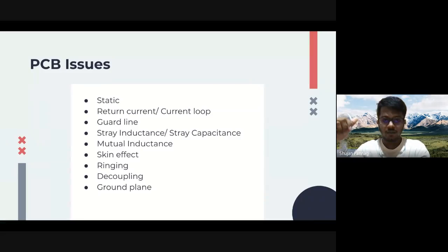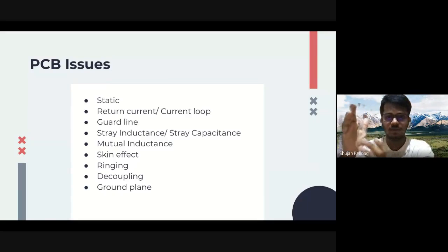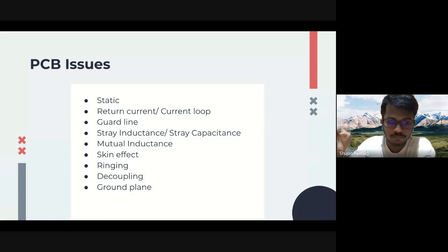Sometimes this PCB was very simple, but when you have very complex circuits, you need to differentiate, in the sense, on a copper clad, which is what the PCB is made up of. Differentiate analog circuits on one side or any side. Keep it a little farther from the digital, just to avoid interactions, and to separate the power planes. I'll get back to the power plane later on.